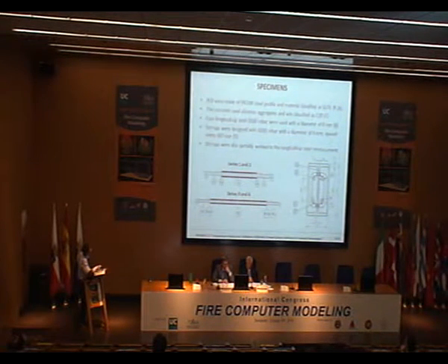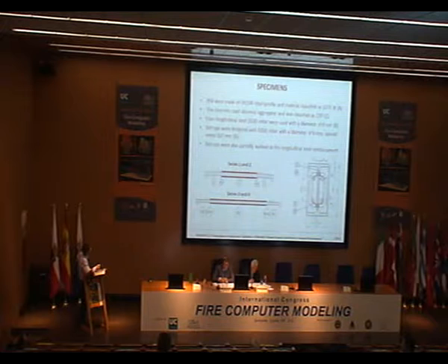We space the tubes every 167 millimeters. Tubes were partially welded to the longitudinal steel reinforcement. This is also important. Here I can show you series 1, 2, 3 and 4. Of course, they have different lengths.